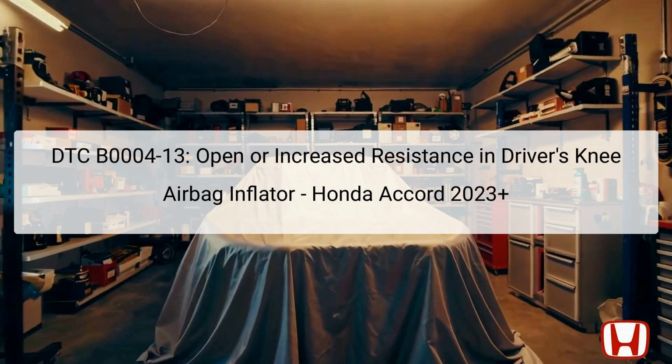The driver's knee airbag is typically located beneath the dashboard near the driver's side footwell and is responsible for protecting the driver's knees during a crash. The SRS unit, or Supplemental Restraint System unit, monitors the airbag systems and records this fault code when it detects abnormalities in the system. It's important to approach this issue systematically, beginning with a review of the vehicle's history to see if it has been in any accidents, which might have caused this fault.